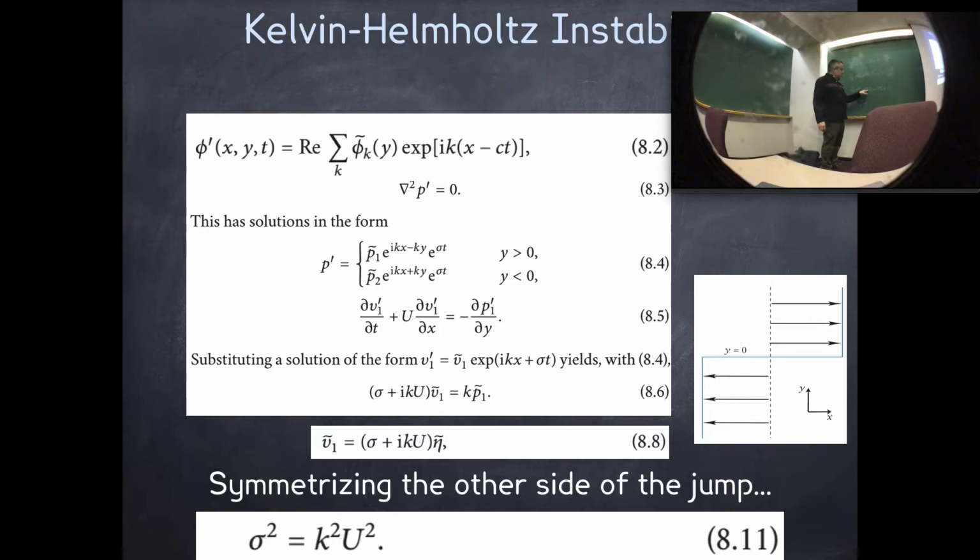And then that one could go with either one of those, but that's 0, so we don't have to worry about that one. But what's the zeta prime one? Zeta prime dot gradient u prime. What happens to that one? Small. It's too small. It's a double product, and we're looking for the linear part. So the only one that we have to keep is zeta prime dot gradient of U.